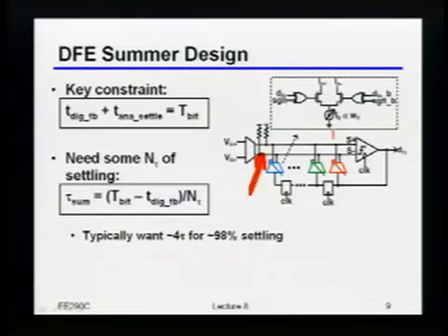In terms of the settling time, or shortest in terms of the digital delay? Digital delay. No, it's actually the shortest settling time. Right, because let's say that this loop is longer, and I want that to settle within whatever time is left. Right? So we'll actually talk about exactly that issue in 1 second, because it turns out you can imagine that is usually longer than the clock to Q delay of the flop. Right? Because for all intents and purposes, this is a flip-flop just with a really small input voltage. Right?